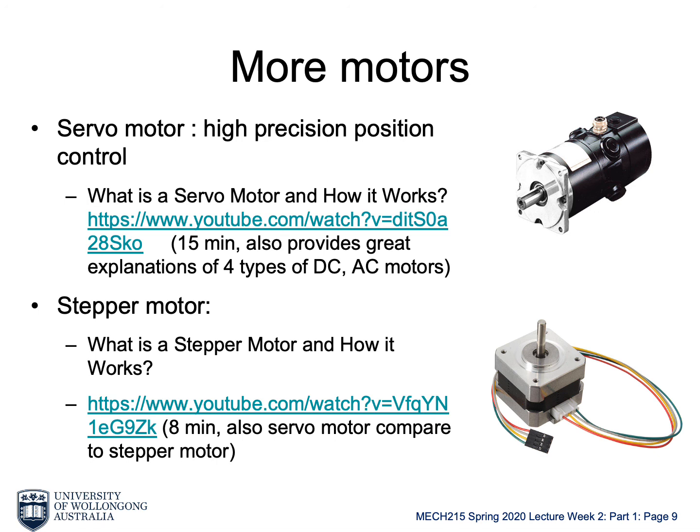For example, if we have an industrial robot with a certain linear movement you want to achieve, in those cases you need to make sure the motor only moves for that certain distance, not continuously. So we need additional sensors and a control mechanism to come together with the motor. So this is not just the motor itself, it's the DC or AC motor plus a certain kind of feedback control.